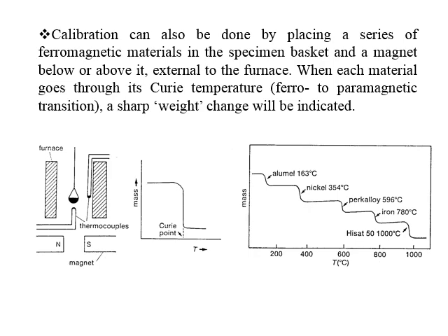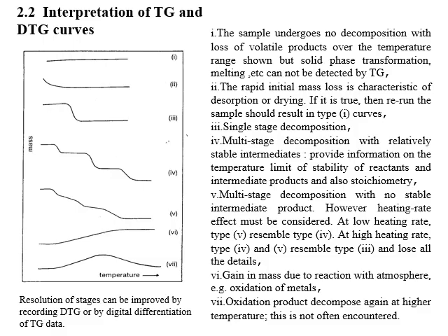So that magnet initially is pulling it down, giving it the appearance of a much higher mass than it really has. And then when you change those magnetic properties, that mass is going to suddenly drop substantially. And this is the way I actually calibrate the TGA in my lab.